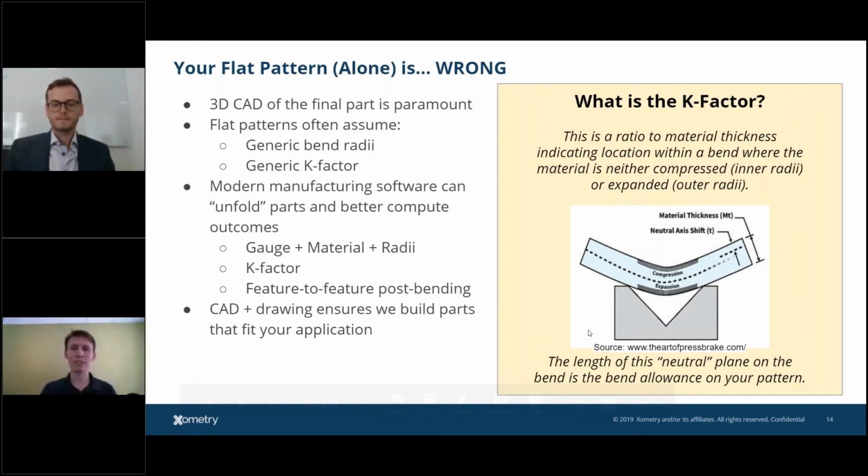And starting with that, just talking about general tolerances of sheet metal, the tolerances get a little layered here because I have a tolerance, for example, if I'm doing a laser or any flat profile cut, it's going to be very similar to CNC where a lot of these location tolerances are going to be right around plus or minus 5 thousandths. But then once you go into things like edge to feature and then you start adding bends, a bend itself all of a sudden will bring in about 10 thou added to that. Because you have little movements and motions that happen within that metal when you're bending.